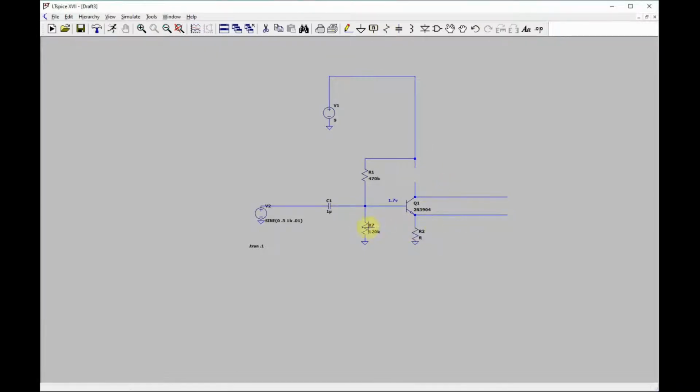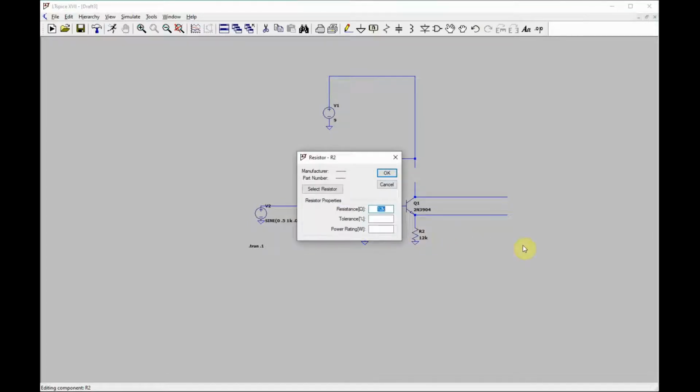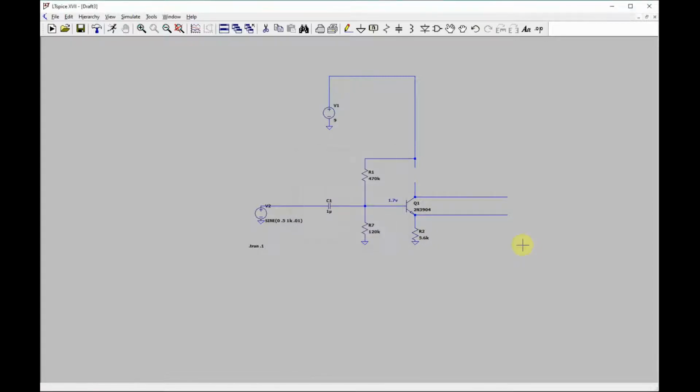So a lot of times I'm doing this the opposite direction. You see 120K there, you immediately want to put 12K in there, but then you can say, oh, I can do better than 12K. I'm just going to cut that in half. A lot of times it's opposite, like if you're building an emitter follower or something. But anyways, you can put 12K there. That would work, but it's unnecessarily high. You might as well go down to like 5.6K. And you'll see later, we'll check those currents going through here and there.